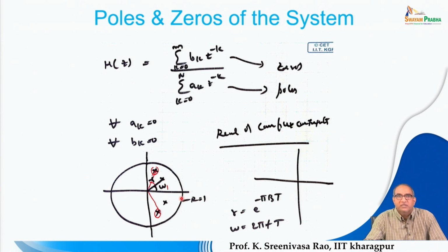So here r indicates the bandwidth, and omega provides the frequency, and as omega increases the frequency will increase, and if the root is real, then the frequency will be 0. You don't observe any oscillations at all. The system response will slowly die out without any oscillations, slowly exponentially dying out. We will see that.